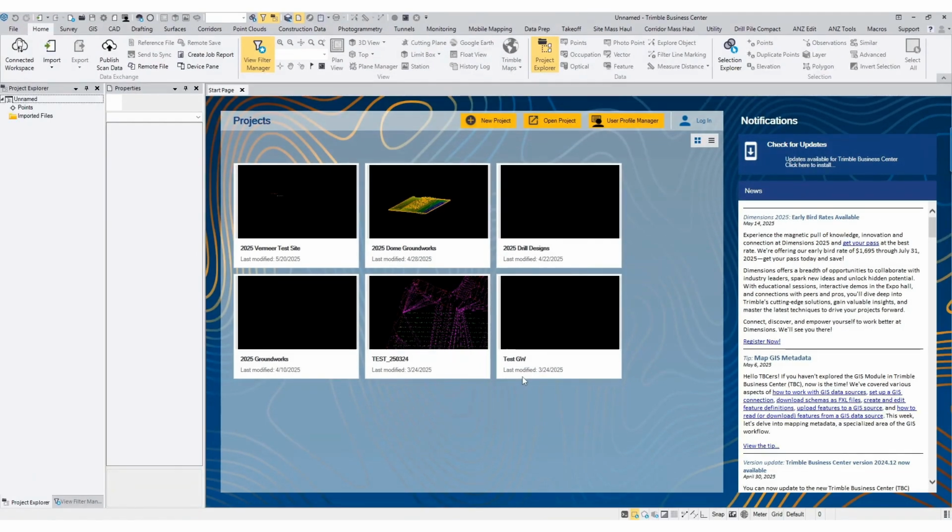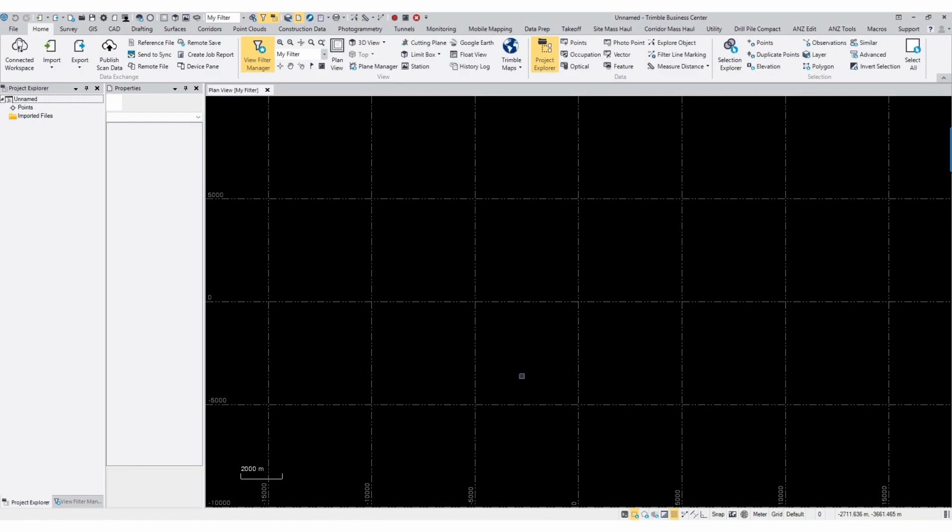Once your new project is loaded on screen, the first step we will do is to ensure we are on the correct coordinate system. This menu will be located on the bottom right of your project. It should say Default. If you have a calibration file provided by a customer, you can import it at this stage instead of selecting a coordinate system.